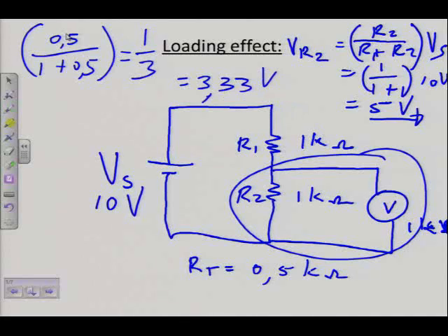That's not correct, is it? It should have been 5 volts. So what you are actually seeing here is the loading effect. What actually happened? Here I've got my total current. Remember, this is a series circuit, IT.